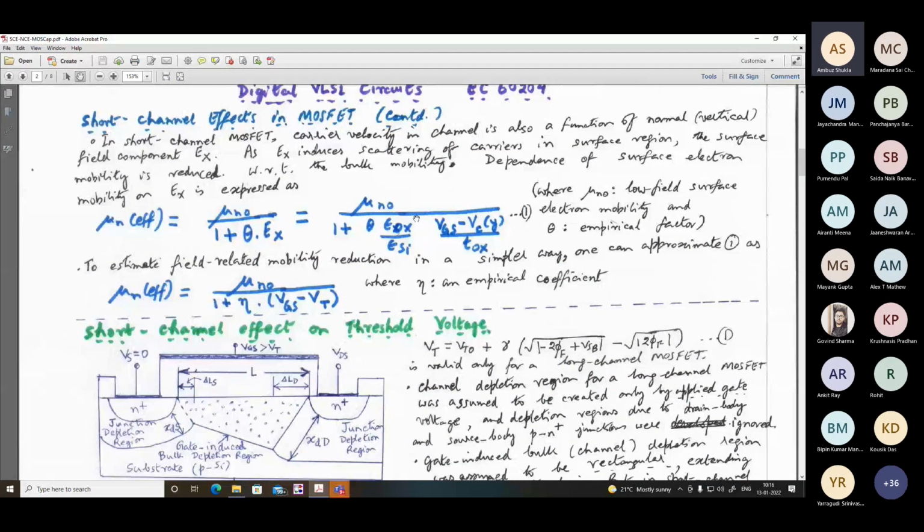So this is theta multiplied by the ratio of the dielectric constant of oxide and that of the silicon. Okay, and then you have the effective channel voltage, that means VGS minus VC(y). So VC, that means the channel voltage, is a function of the dimension Y. That means as you move from source to drain, it will progressively be lower and lower. It will be more reverse biased, right? And divided by the oxide thickness.